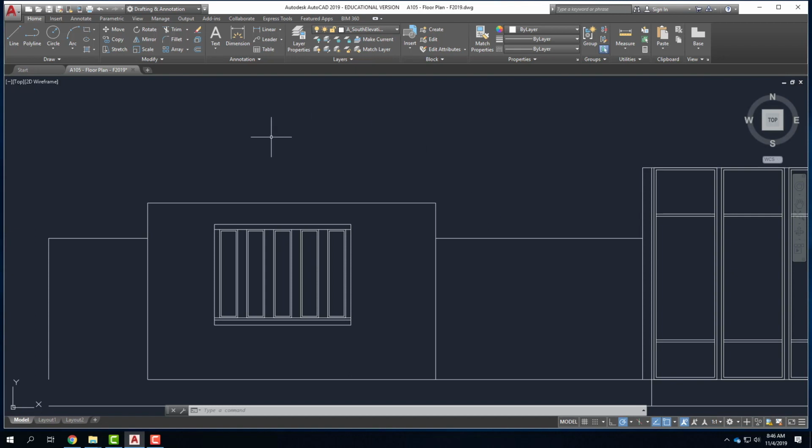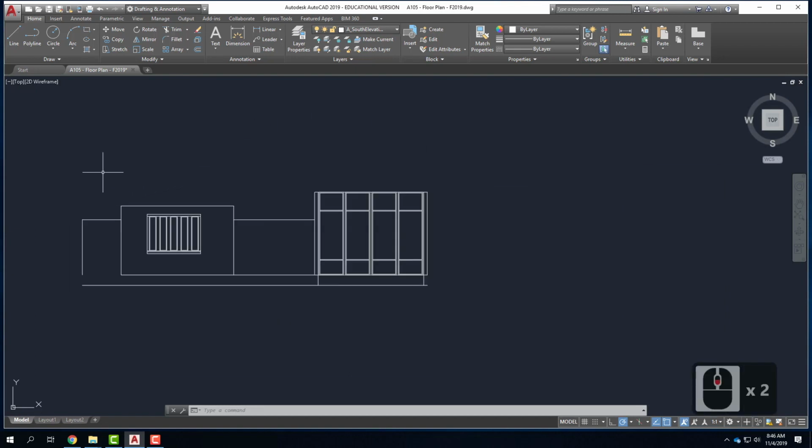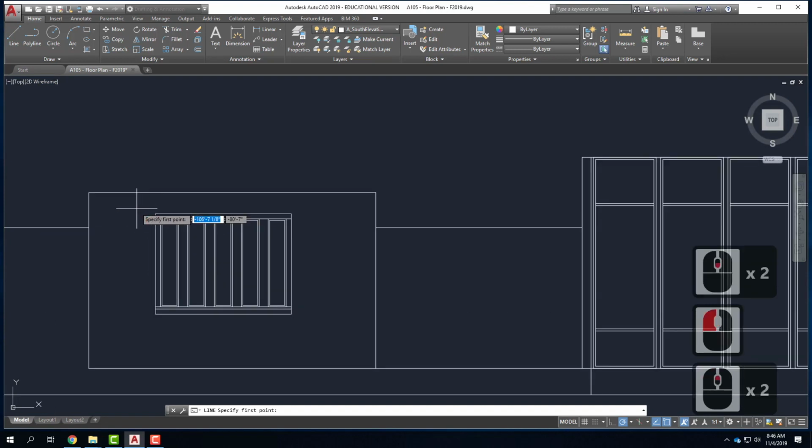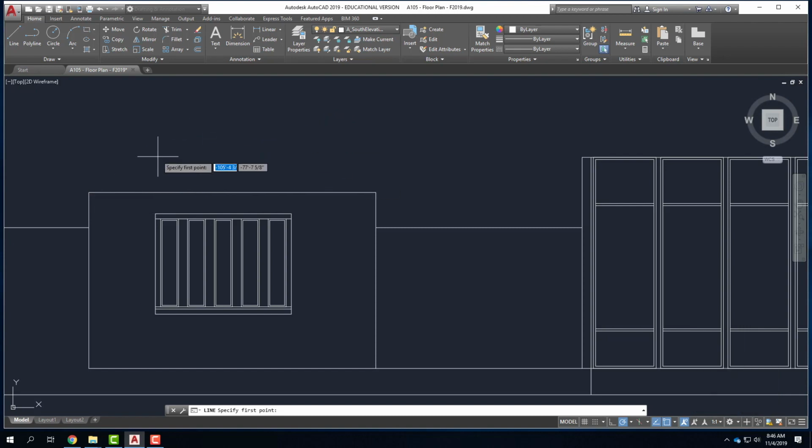And so this is going to depend on the look. So if we start with, say, a 6 and 12, I need to be able to go from this corner and know what 6 and 12 would be. So for me personally, I don't know what the angle of a 6 and 12 is. I do, but I'm not going to tell you the angles because it's something you have to keep track of. And instead, this is a perfect opportunity to use those coordinates, the relative coordinates. So I could say here, I want to go at, and then I just need a multiple of 6 and a multiple of 12, if that makes sense.